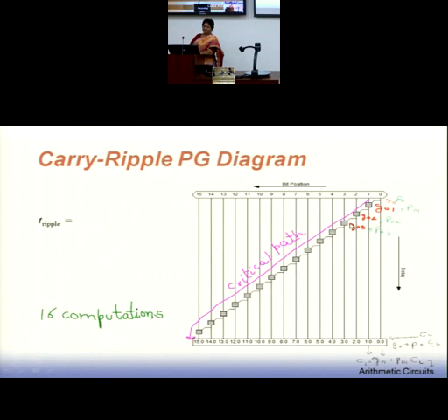So either you draw it in that way, or what I do is that I have a G0 P0. I use it to compute the block of 0 and 1 together. Generate for 2 bits together, get me G01. Generate for 3 bits together, 0, 1 and 2, gives you G02. Generate for 4 bits together from 0 to 3, G03, G04, ultimately G0,15.